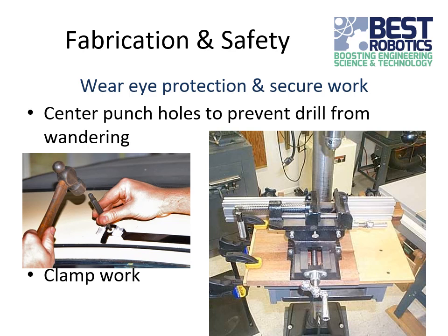And then clamping your work is always a good idea. If you're using the drill press, you need to make sure it's clamped down to the drill press table. A lot of times there'll be a vise attached to that already that you can use, but if not, you can clamp it down with normal clamps.